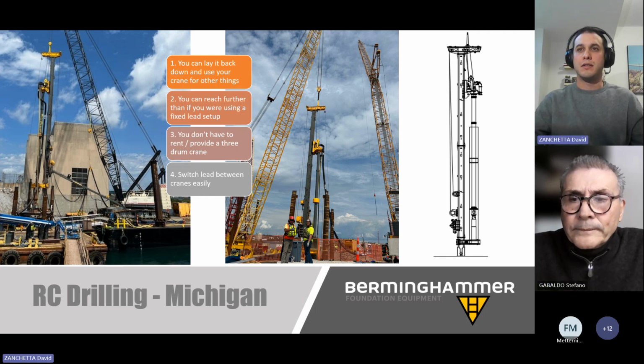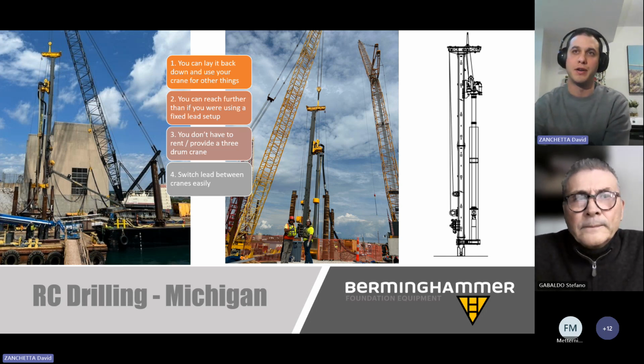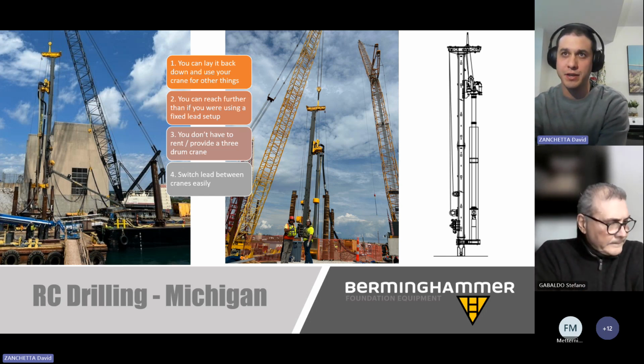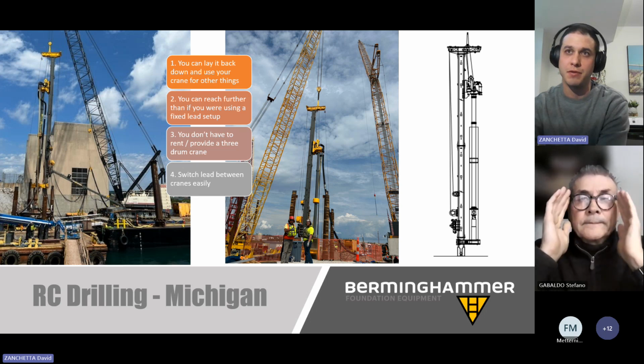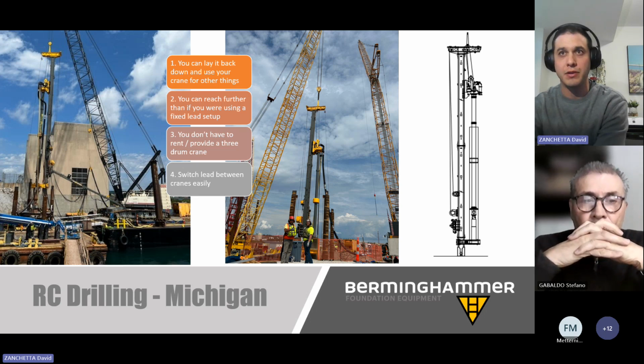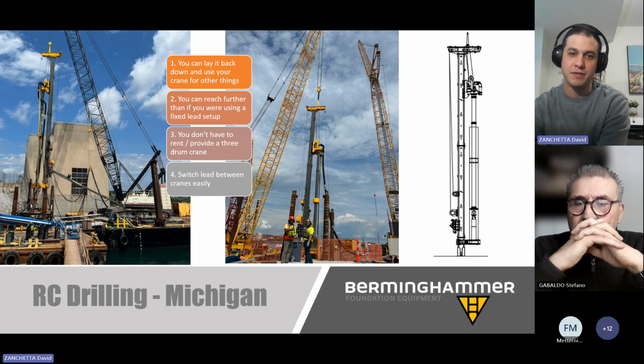Kim Coffee asked, are you powering these winches from auxiliaries on the crane? And I think I can answer that one, as most of the time it is system specific. Some cranes have the auxiliary functions to be able to run these. Some of the really duty cycle cranes out there on the market can run all of these functions without any additional power pack. In quite a few cases where we're providing rental systems, we'll use a power pack that we have that already has built-in valve banks and controls to be able to run all of these. And typically we are mounting that on a power pack bracket on the reverse side of the crane.